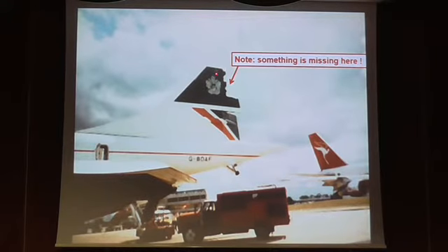This was not an Anglo-French design argument here. It came in and it had lost the rudder section due to fatigue. Of course, there is a backup of the second rudder section. So it does occur, we do get fatigue failures, and probably more in military aircraft at times. They're flying harder and faster than the civil ones, but it is a real problem.